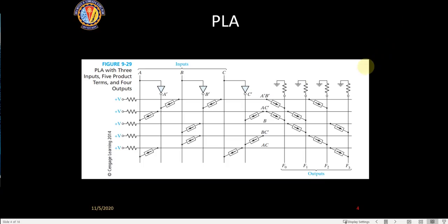If you just take the first line, whenever A goes to 0, then this would get shorted, right? I mean, all the current would flow into the ground. No. When the A goes 0, the second row will go to 0, because there is a diode connected here. Oh, okay. Those aren't connected. Fine. I'll just explain that aspect. When the A goes low, this is connected out here. Assume I have put a 10k resistance here and it's a 10 volt.